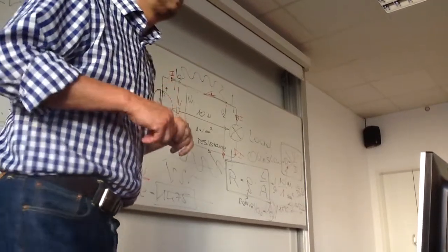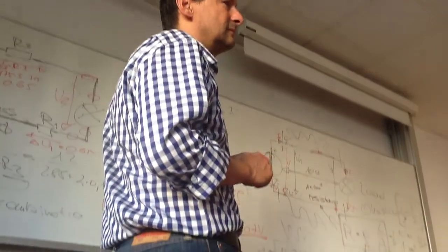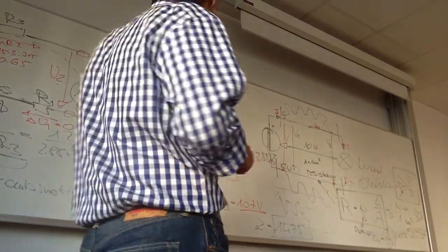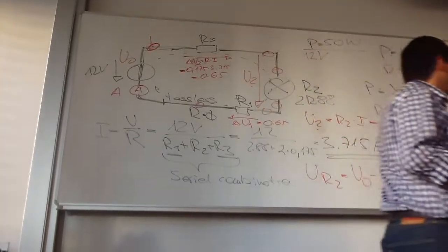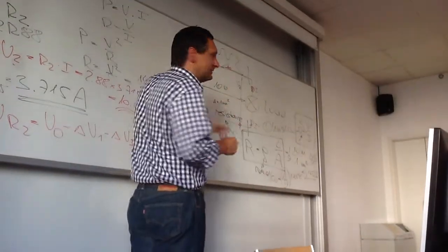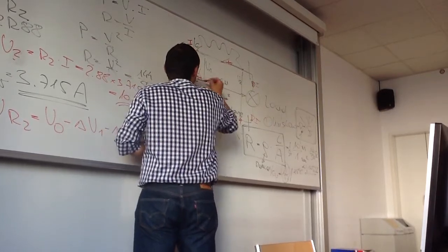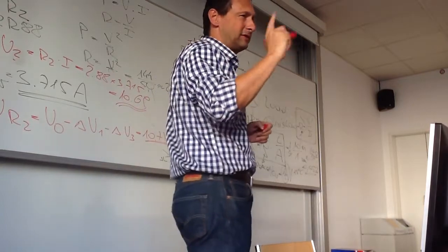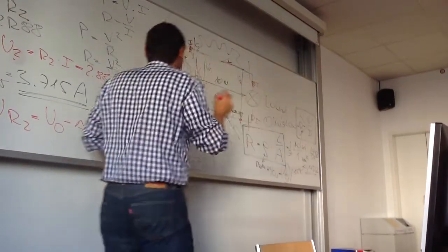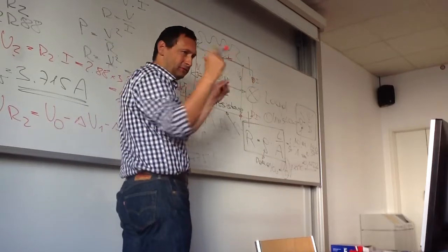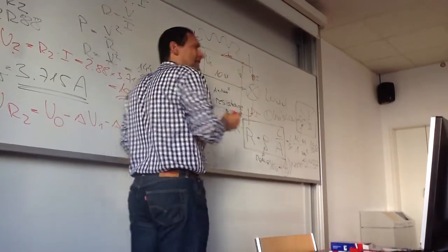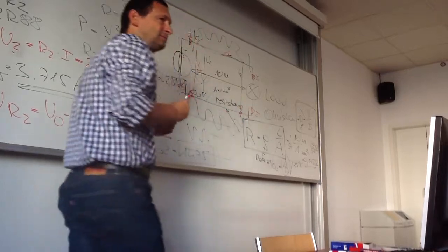The things which we calculated before show that we don't have any losses of voltage after R2? Yes, there is loss. So if you take a voltage instrument and do your measurement from here to here, that's the basic difference of the two measurements. For current measurements, you have to cut the line, put your instrument in, and the current can again flow.